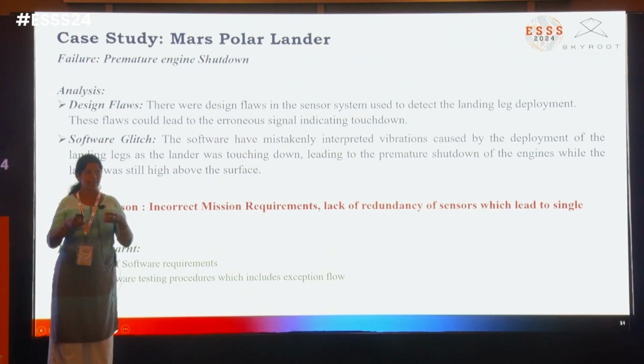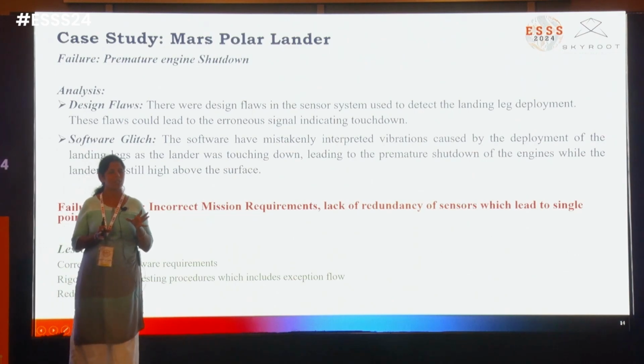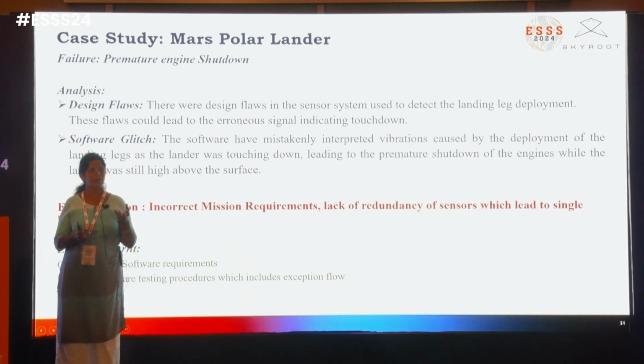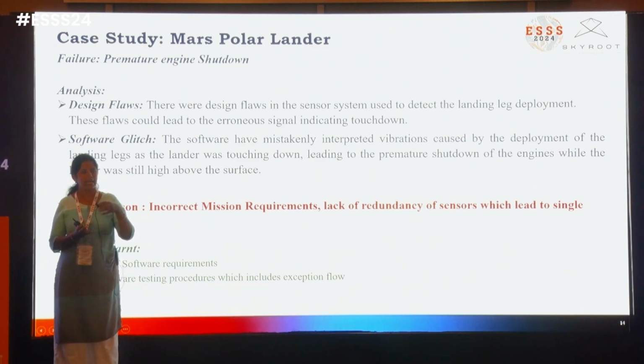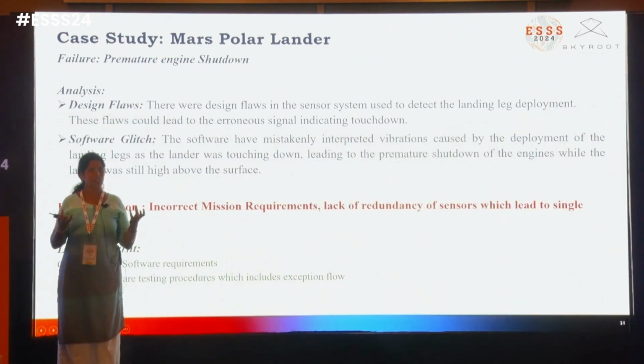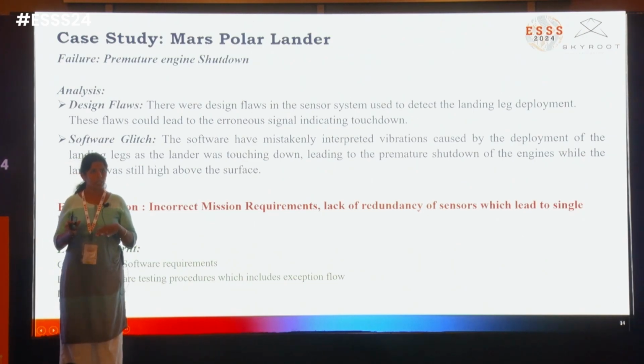There were landing legs, and the mission failed due to premature engine shutdown. So what caused this engine to shut down without touching the land? The landing requirement was captured such that whenever a vibration is sensed by the sensors, the lander assumes that it has already touched the ground, and that leads to engine shutdown.